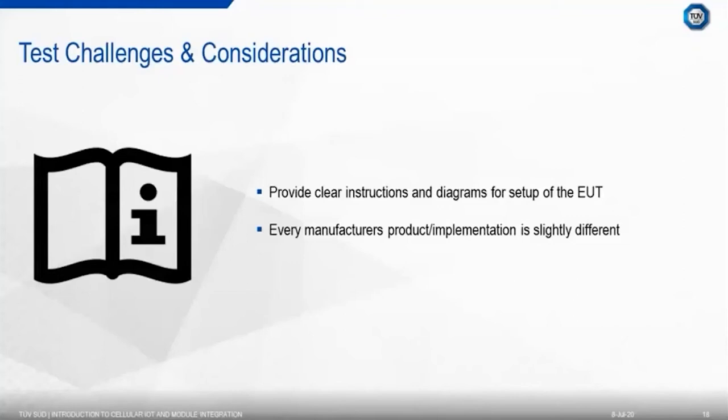There could be some cases where additional effort may need to be considered prior to testing to modify the main application or to provide a test application to enable testing to be carried out. An example of this could be a product which needs to access an external server. If this server is not seen, the link will be dropped. There are ways to configure the test set to enable access to the outside world, or alternatively a modification to the application software to remove the dependence on that external server. It's recommended that prior to starting any testing, consultation with your chosen lab is done in advance to save any delays at the time of test.